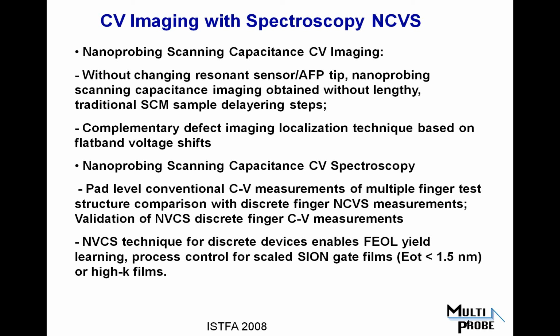characteristics like Miller capacitance on particular discrete devices. So our outline is we're going to first talk about CV as a general method and compare it to the nano spectroscopy methods on discrete devices. We'll talk about scanning capacitance and its role in failure analysis and try to describe the capacitance imaging contrast technique as a new method for identifying dopant-type defects.